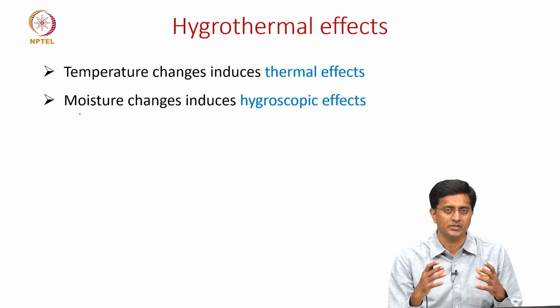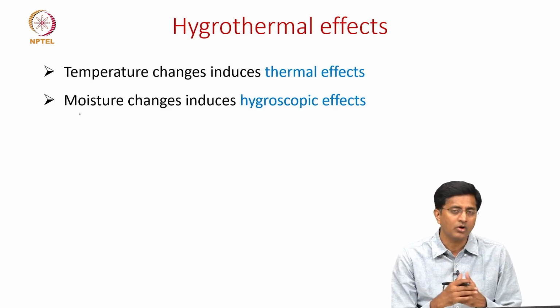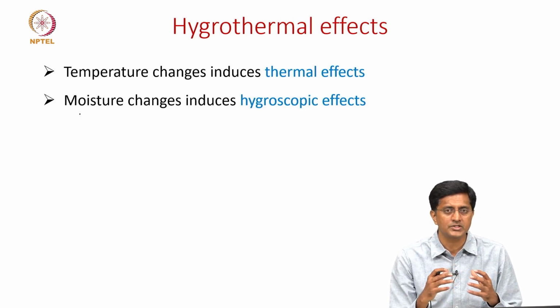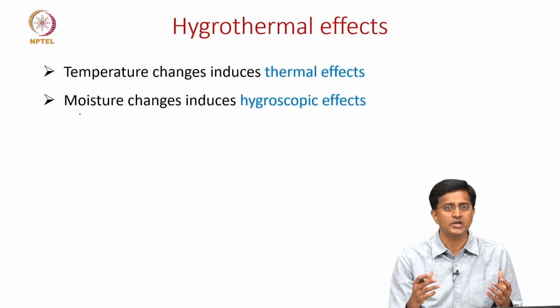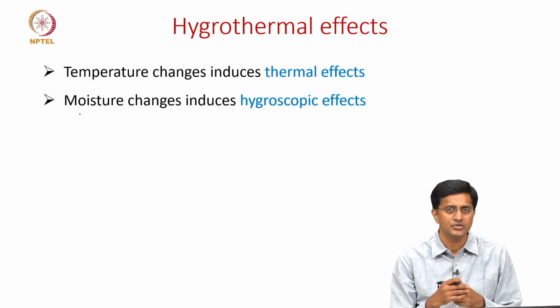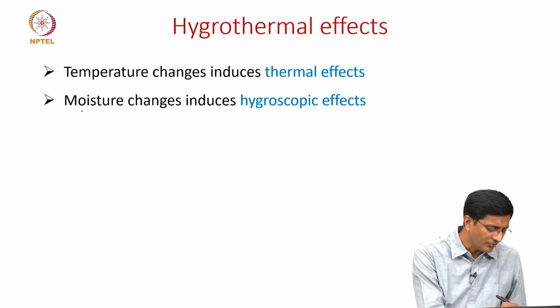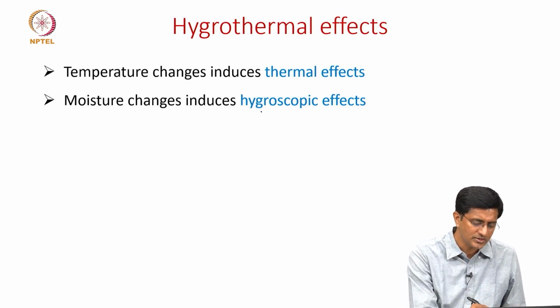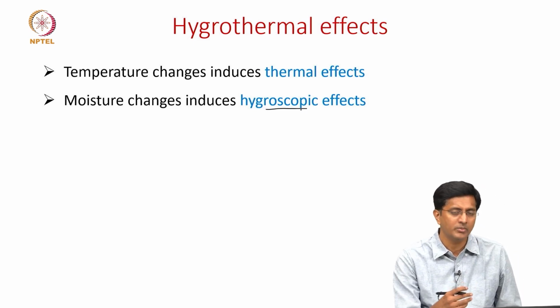volume of the material. It's not always true that all composites have this swelling, because there are some composites where with increase in temperature or humidity, there might be a decrease in the size of the component, which means they have the negative effect. But when we are discussing moisture changes, we say that it induces hygroscopic effects. Hygroscopic meaning the water molecule related effects.